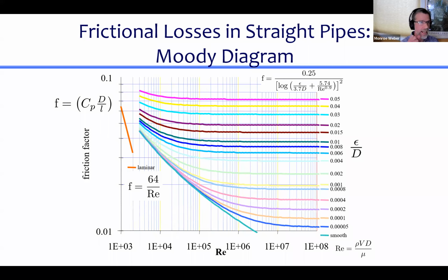Remember, I just said that a high Reynolds number means that inertia, or the effective velocity and density, is big and viscosity is small. And that means that viscosity is insignificant. Reynolds number is a measure of whether or not viscosity is significant. At high Reynolds number, viscosity isn't significant anymore. And so there's no longer any change in these curves. They go flat because the only thing that matters is inertia, and that's kind of constant.